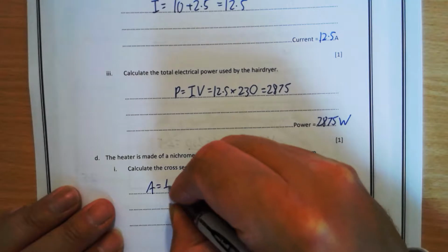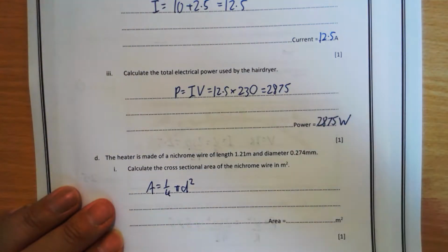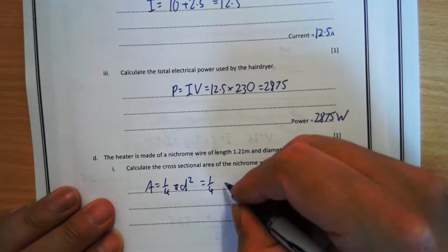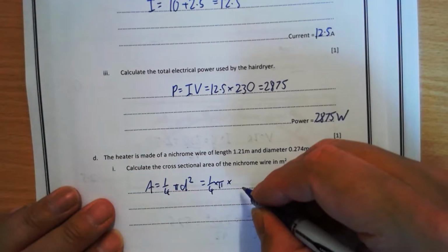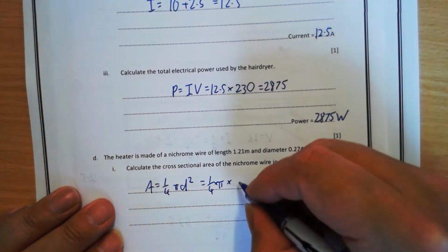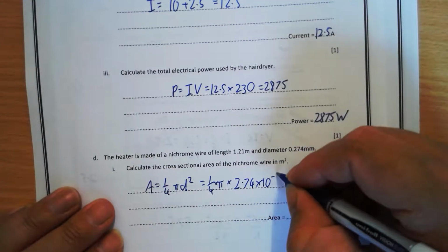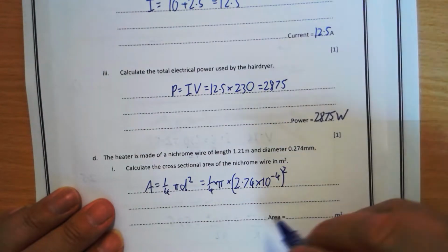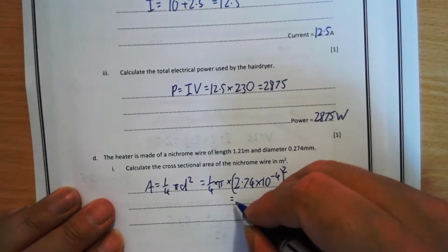The area is using 1/4 pi d squared. So that's 1/4 times pi times d squared. d is 0.274, so that's 2.74 times 10 to the power minus 4, all squared. So you square that whole expression there. And that should come out to be